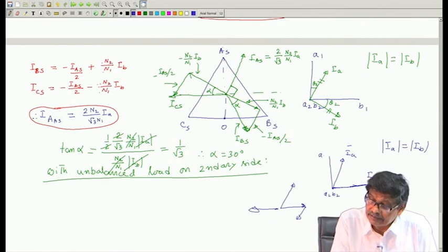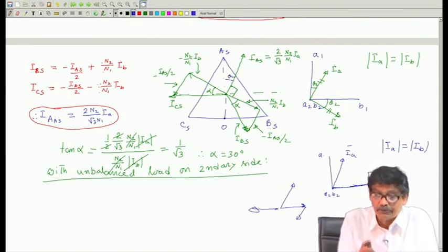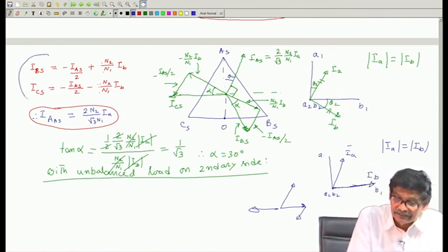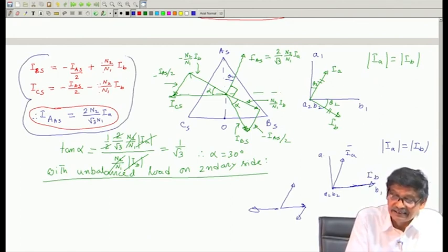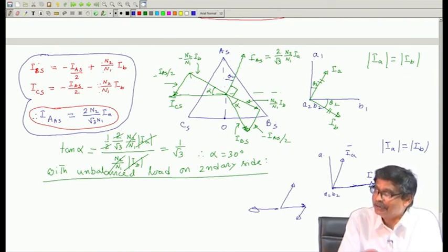Because this is the phase voltage of the primary side, and I A S lags it by an angle of theta 2. If the secondary current is unbalanced, the primary current is unbalanced, but what I am trying to tell is that these equations for I A S, I B S and I C S are true no matter whether you have connected balanced load or unbalanced.